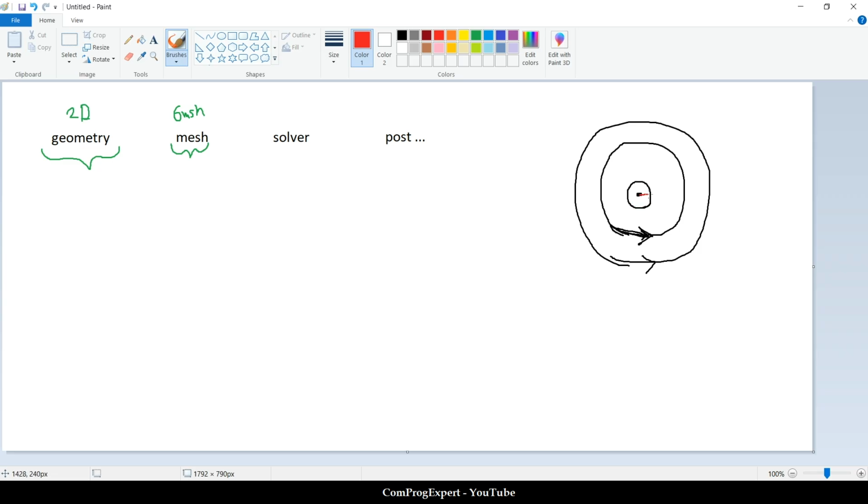As you know, if we consider this as the radius of the wire r, we can use the Ampere law, integral of H dot dl, is equal to the current that is inside the enclosed surface, and finally calculate the value of the H. And if I consider this x-axis and this as the y, this is the By along the x. You know the analytic solution is simple.